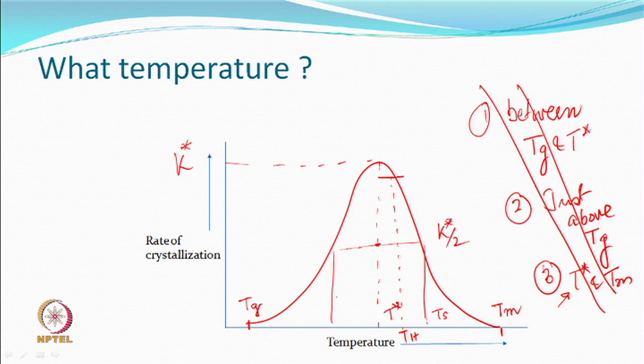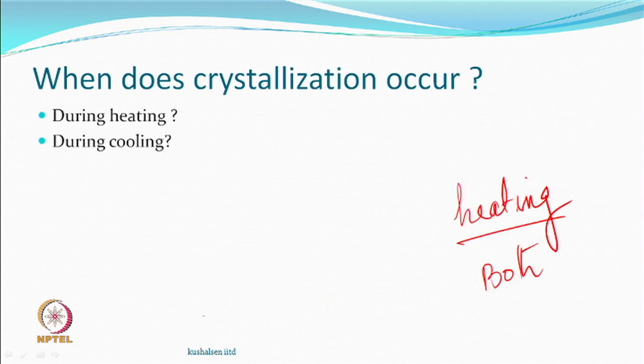The rate will keep going down as you cool, and you may actually go below the glass transition temperature, as we said. After that you will be safe, no more change can take place, and you may like to cool as much as possible, but we definitely must say that during both these processes crystallization can take place.